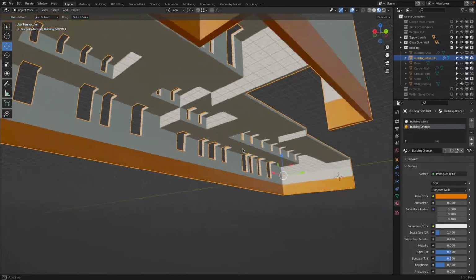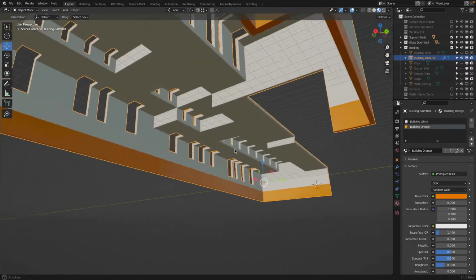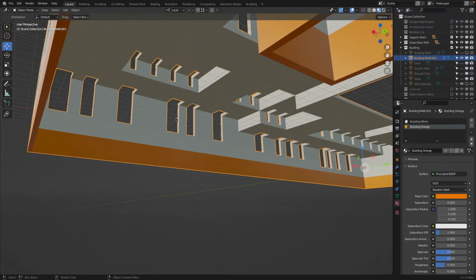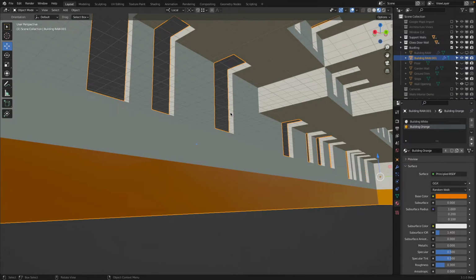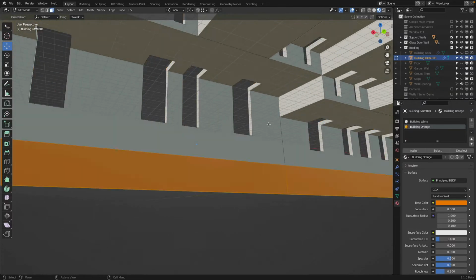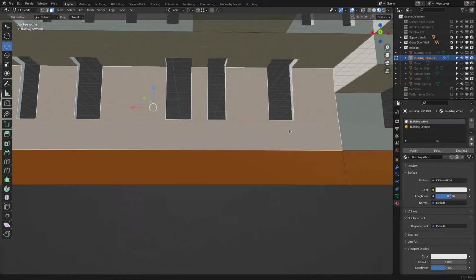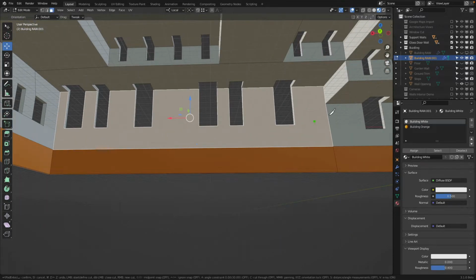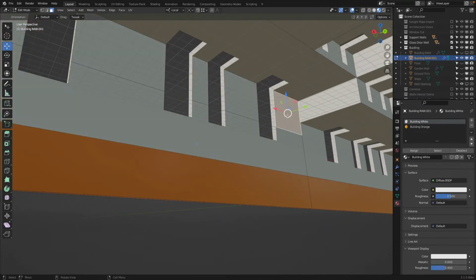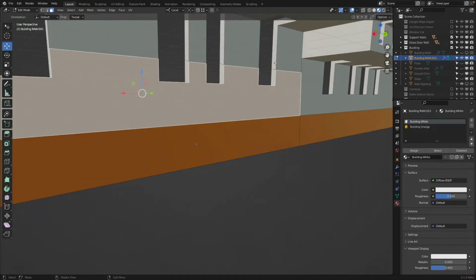So how can we now make the material go through the inside here, and maybe stop at this wall? And then we have a little bit also in here. So there is my piece now. So I have this face selected. I can press K, click here, and then X till there, click enter, and that's it. So you see this face I sliced.